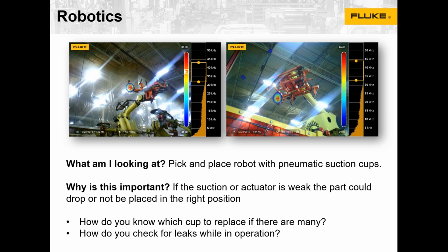Or if it was just having a suction issue, they would shut it down and they would replace all of the different cups, which in some cases is a lot and pretty expensive, just to make sure that they address the issue. They were able to use acoustic imaging technology to not only do the troubleshooting while the unit was running, which just made it a lot easier, but also they were able to pinpoint the exact location where the issue was happening, so they didn't have to do a complete overhaul or a complete retrofit on the piece of equipment just to hopefully address the issue.